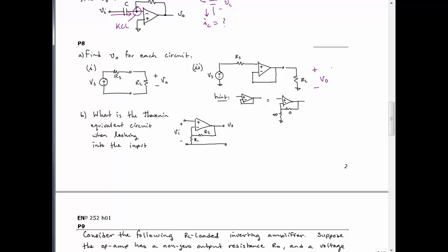In the first case, there is no active device. An active device would be like an op-amp. All we have is a source resistance RS with Vs. It's kind of like a Thevenin equivalent, if you will. Maybe it's literally a voltage source and an RS, but maybe it's something more complex that we can just represent as Vs and RS. But in the first case, it's a simple case of voltage division. Vout is going to be less than Vs. There's nothing you can do about that. The degree to which it's less than Vs depends on the relative values of RS and RL, and you should be able to write an expression straight up for that.